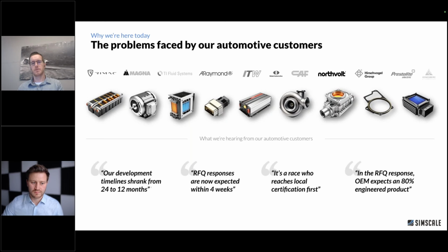So we use some 1D solvers that have some 3D capability, but 1D engine specific software that allows us to get things like flow rates, allows us to get things like temperatures. It's essentially a virtual test bed for us that we can pull forces and all these other boundary conditions out of to apply to a part that's created in CAD that now exists in SimScale.